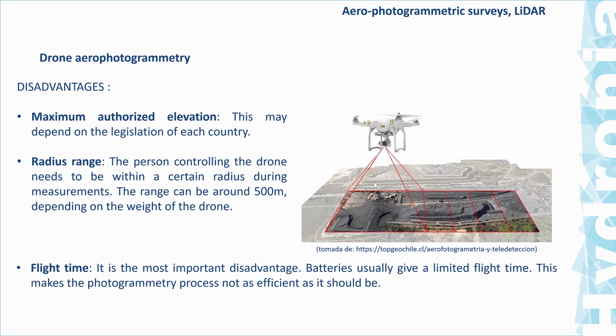Now, some disadvantages are that the drones cannot be flown at very high elevation, so that restricts the areas that you could survey with them, and this typically restricts the areas to smaller watersheds or smaller urban areas. Also the flight time is limited because of the battery duration of these devices.